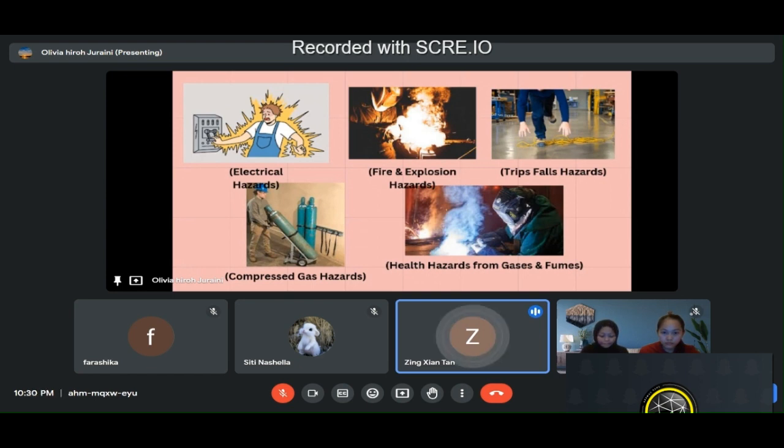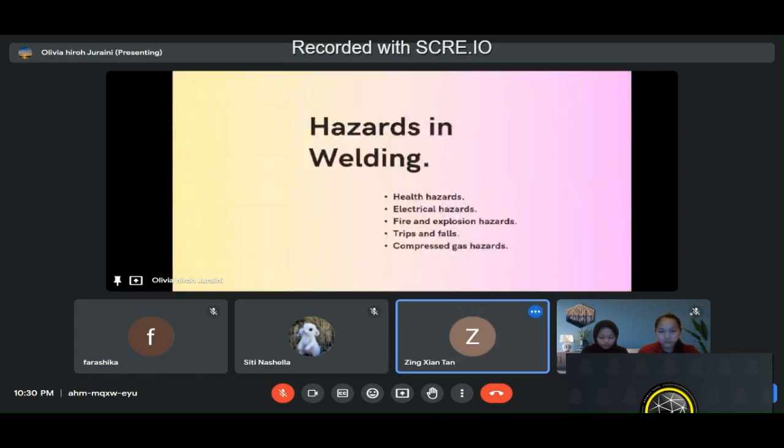A fire or explosion can be caused by intense heat and sparks when near combustible material. Therefore, welding should only be performed in areas free of combustible materials. Containers containing combustible materials should never be welded unless the containers have been purged or filled with inert gas.